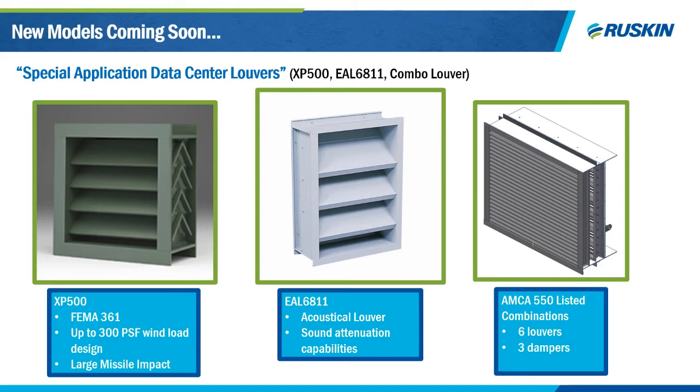The next one you see there, the EAL 6811, you might notice that louver model looks slightly different than the others. The blade you can see is a little bit thicker. That's because this is an acoustical louver. So not only is this one keeping rain out and allowing airflow in, but it's also attenuating the noise from inside the building.